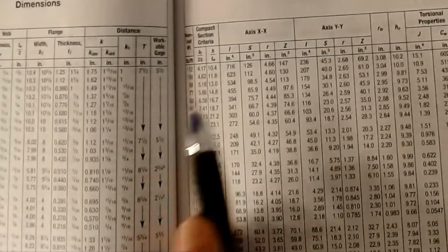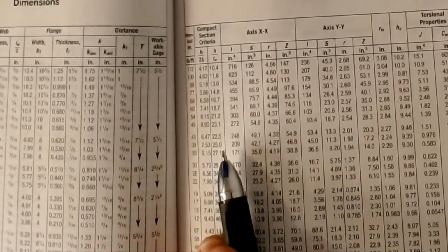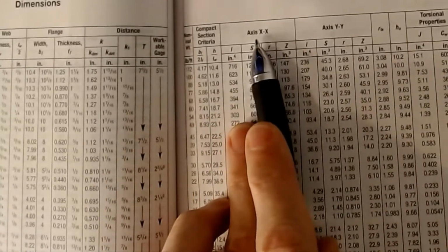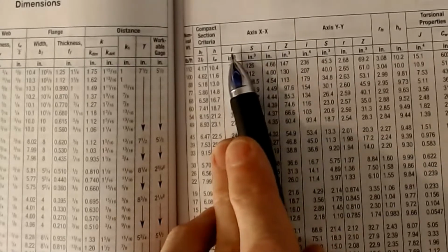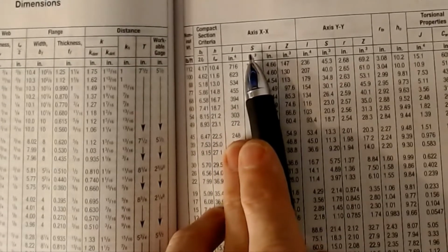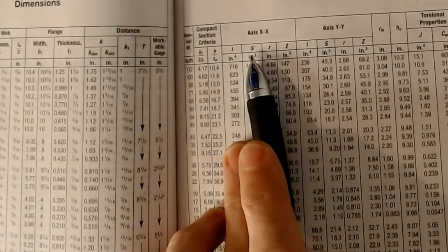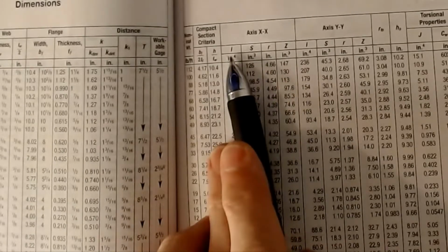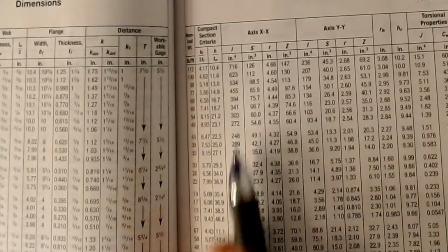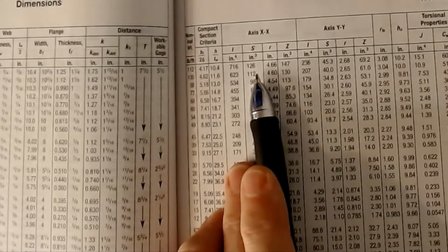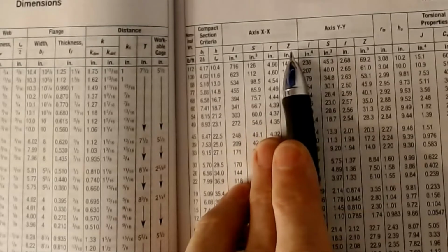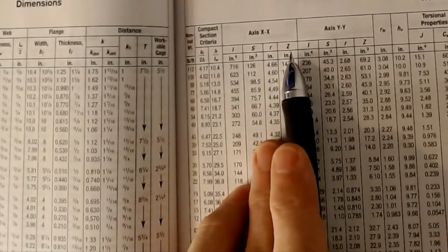Okay, over here we also have the moment of inertia, I. Okay, so that is the moment of inertia about the centroidal axis of our shape. Okay, now notice that this says with respect to the x-axis, so this is Ix or Ixx, depending on how you label it. The next one is a section modulus calculation that we're going to use when we get into flexure that is also about that axis. This is basically I divided by, in this case, half of the height, which gets you this value. But it's a number that we compute often enough that they've gone ahead and tallied it to save you time having to do that calculation. R is Rx, that's the radius of gyration, and then Z is Zx, which is the plastic section modulus, another flexural computation that you'll need.